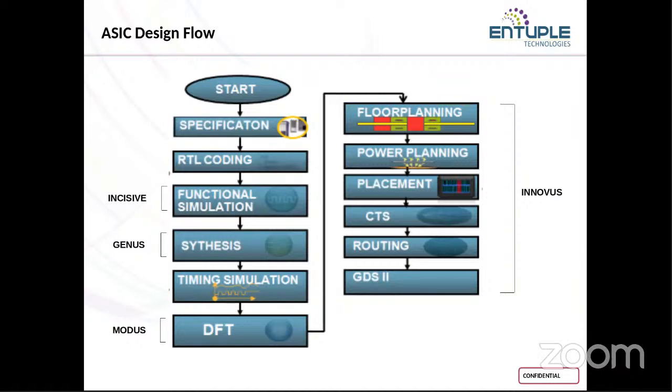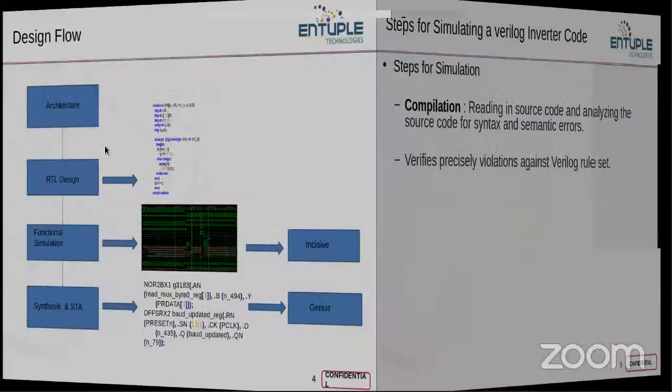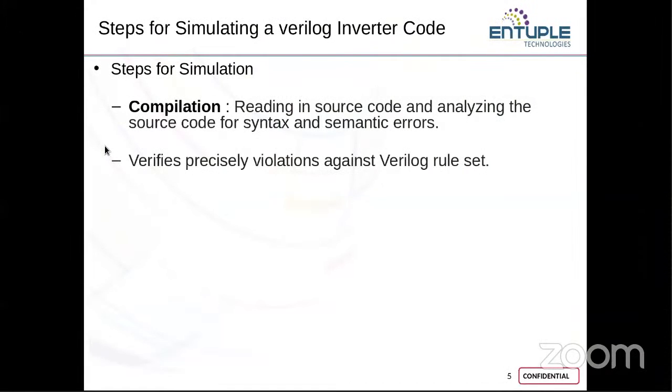The first one is your compilation, where it will be doing syntax checking. Whatever RTL logic you have written, it will check the syntax, analyzing the source code for any errors in your syntax. All those things will be checked under your compilation stage. So that is your compilation.